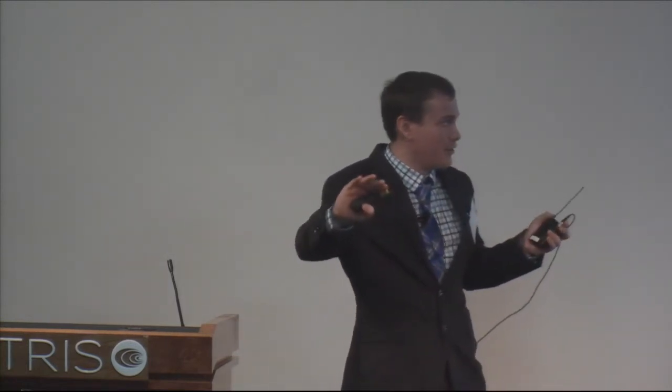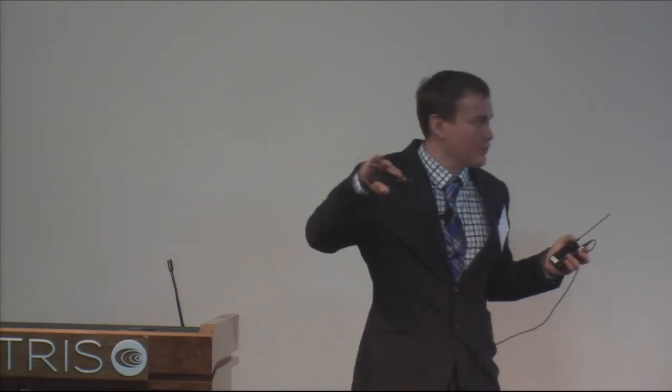Once again, it boils down to some of our ab initio models. We assume that when we scale below a certain threshold, we have a completely different spin dynamics. And yes, you're right, the current is smaller, but more importantly, it's the current density. In theory, there is linear scaling. As we scale down the current, we don't effectively scale down the current density. So we see an extra order of magnitude in terms of switching energy.